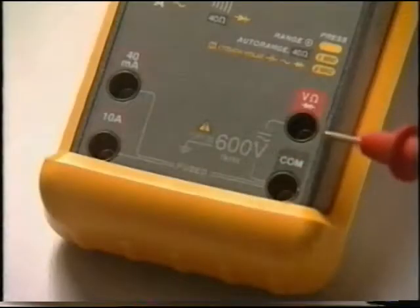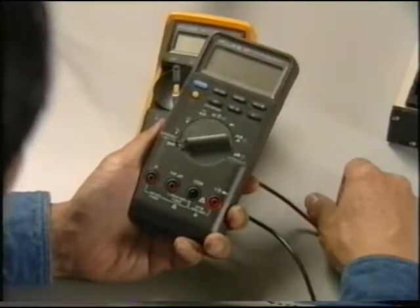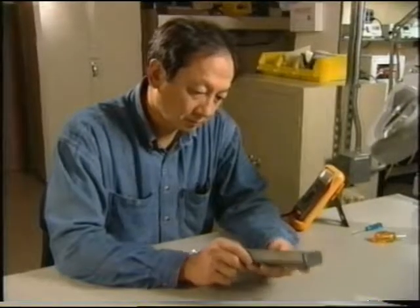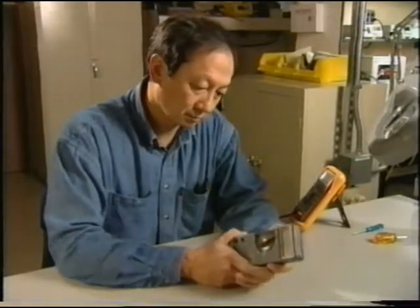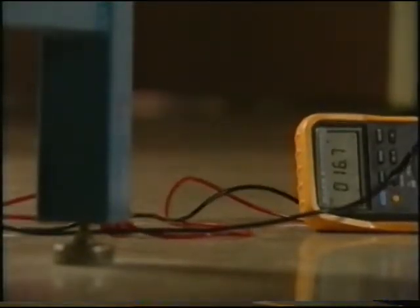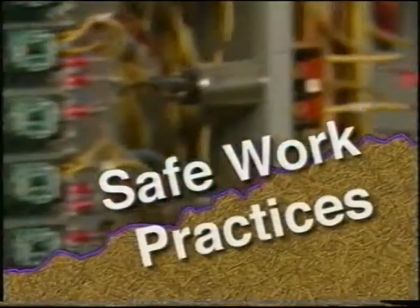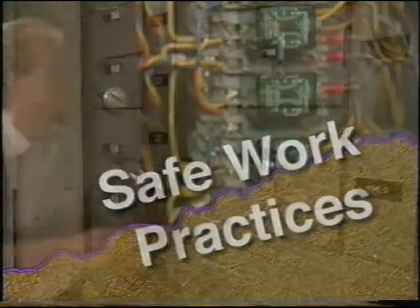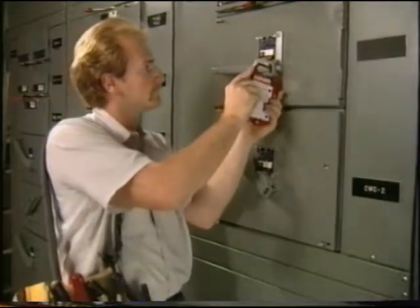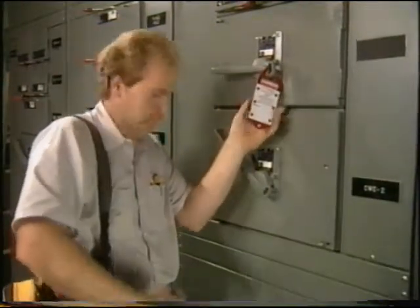Look for a meter with recessed input jacks and high-quality non-conductive case materials. All these important safety features should be protected by a tough, industrial-strength outer case. It seems obvious that a meter should survive a fall from a test bench or work ladder. Safety results from using the right tools and safe work practices.